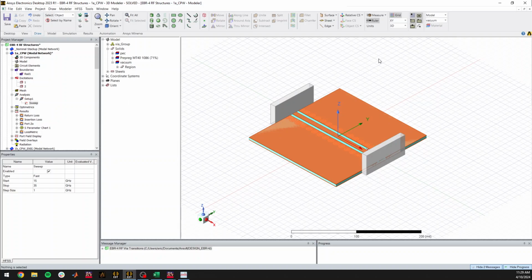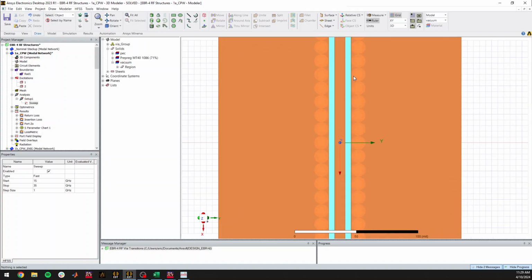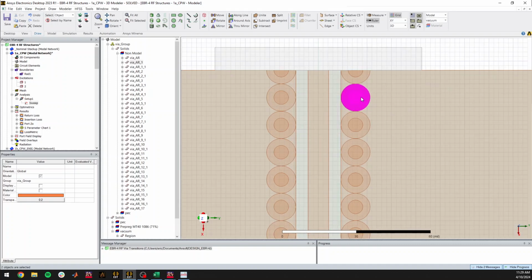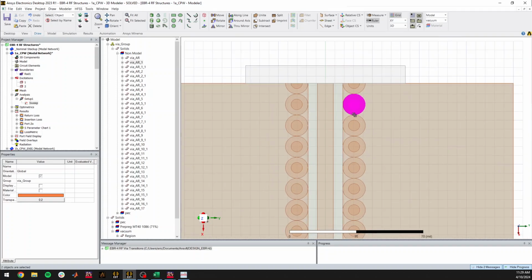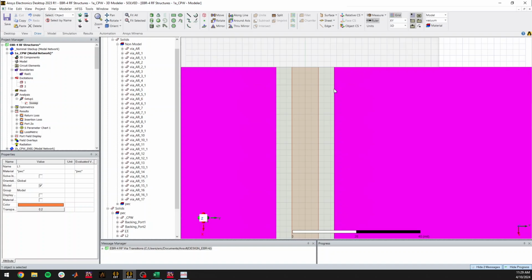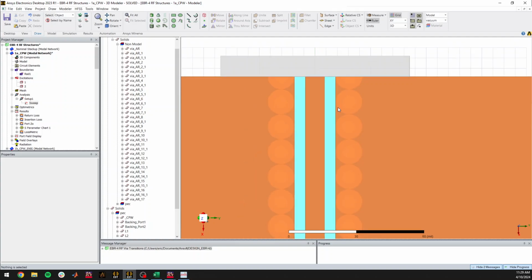And so you can have an initial design worked out in terms of the relative trace width and spacing and your via spacing. What I'm showing here is a via with some given radius, and then this is sort of like the via pad or the annular ring. And you can see it's butted up right against the edge of your copper ground pour. So this is something you may need to give some padding or margin to based on your fab house. Some fab houses will put in these vias, and then this ground pad will be etched back, and your vias will actually be kind of sticking out in your ground pad.